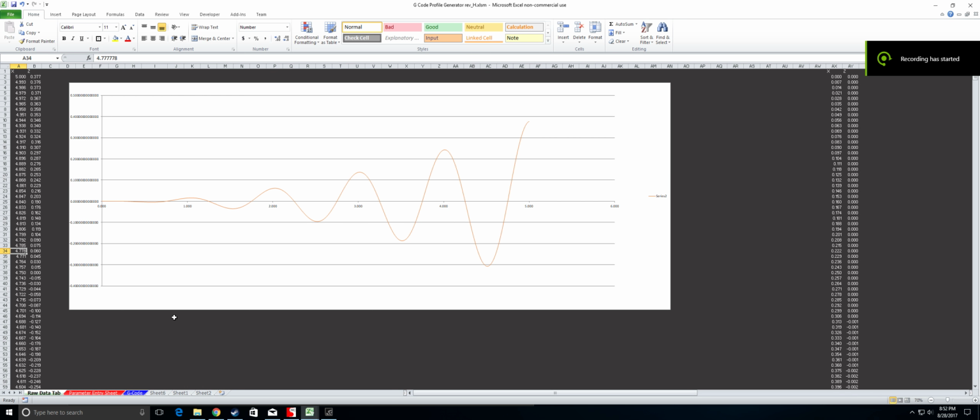Alright, hi guys, I'm going to go ahead and reintroduce this form, I should say, since I've made quite a few updates to it. If you remember, this is the form where you take a pattern in terms of XZ data and you can generate looping G-code to machine the pattern. It's predominantly targeted towards a Nanotech 350, maybe a 650 FG. It may work on some of the other ones, but some of the G-codes may be relatively specific to those machines.